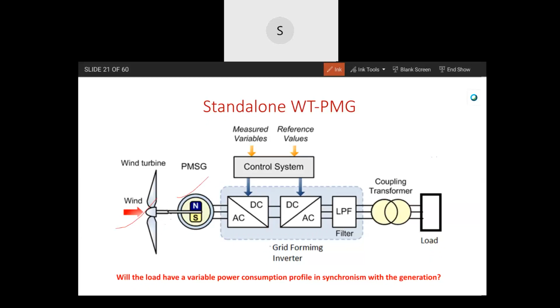So the size of the machine is just like a ceiling fan. The ceiling fan itself has 18 poles. It's not permanent magnet, but another way. And then it needs an AC/DC/AC interface to rectify the power, because, as I told you initially when we were discussing, for every wind speed, for the power flow equilibrium, power transfer balance, a different shaft speed is required.